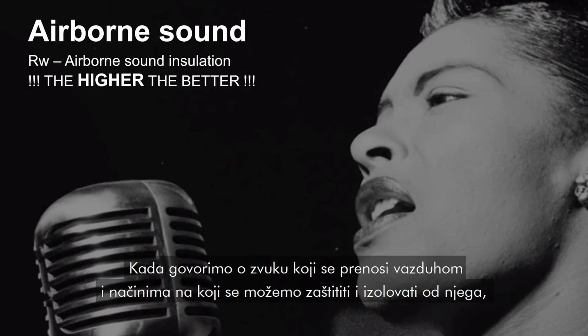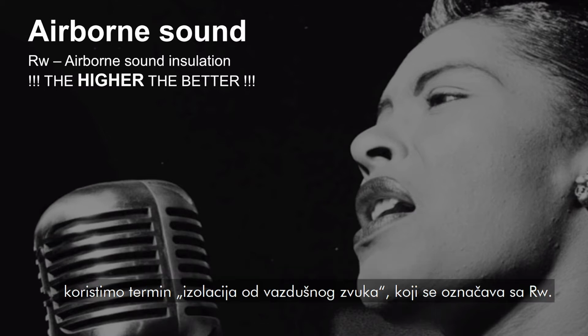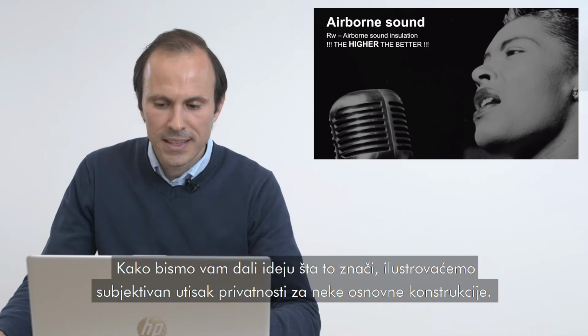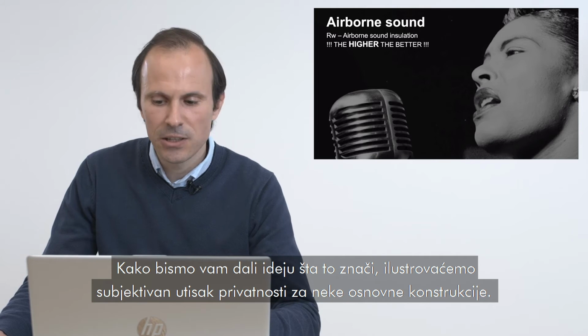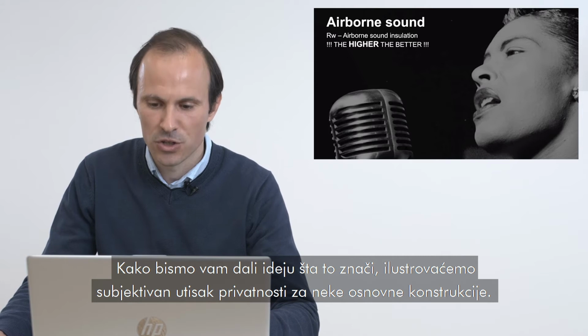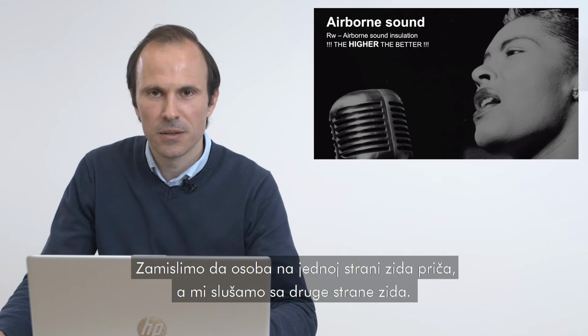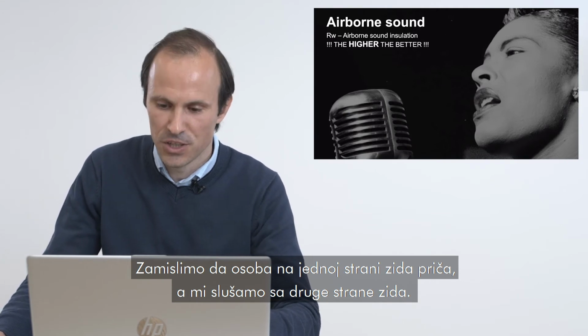So when we talk about the airborne sound and the ways to protect ourselves from it, to isolate ourselves from the airborne sound, we use this term airborne sound insulation and we denote it with Rw. And we say that the higher this Rw is, the better it is. And to give you an idea what this means, we shall illustrate the subjective impression of privacy for some basic constructions. So now let's imagine that the person on one side of the wall is talking and we are listening on the other side of this wall.